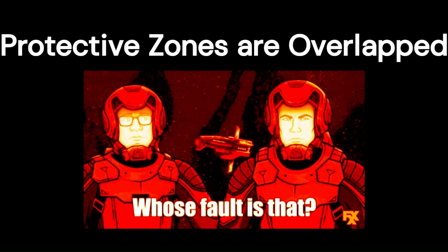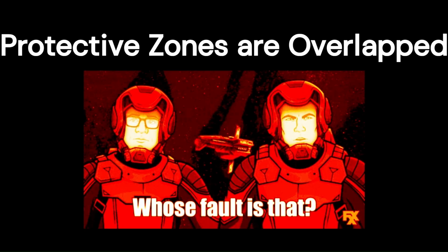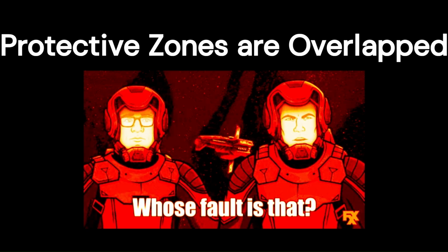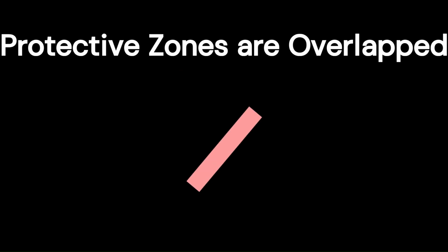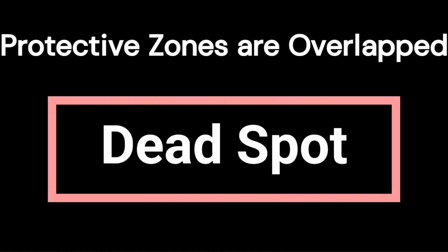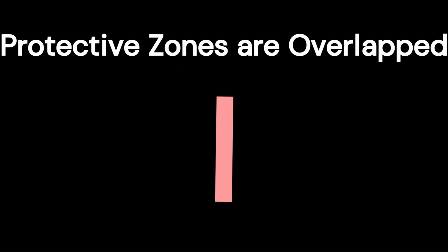Without overlapping, a fault occurring at the exact point where two protection zones meet could be missed by both protective relays, which can create a dead spot where no protection is activated.